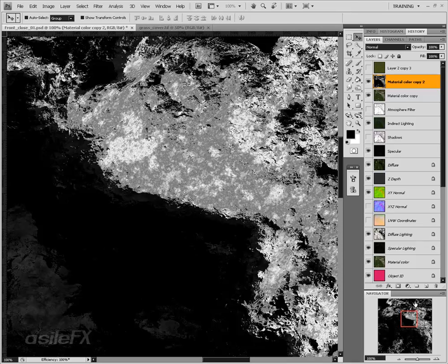I do want to note that Vue's anti-aliasing is typically too low with all of the presets. And I normally suggest rendering larger and scaling it down, especially for animation if you're having flickering problems. Render about 30% larger than it needs to be, and then scale it down in post, resampling.